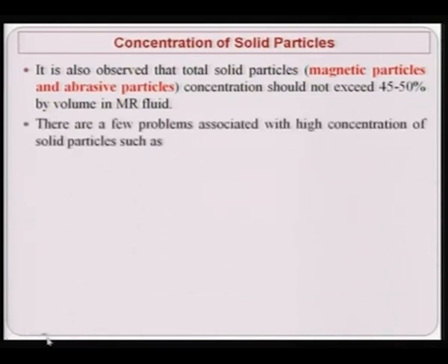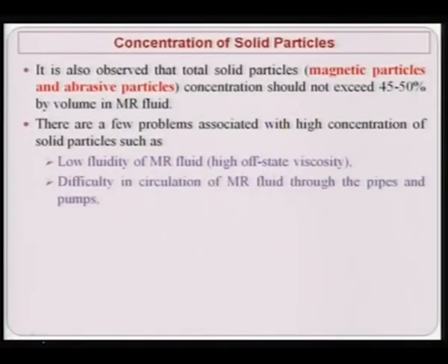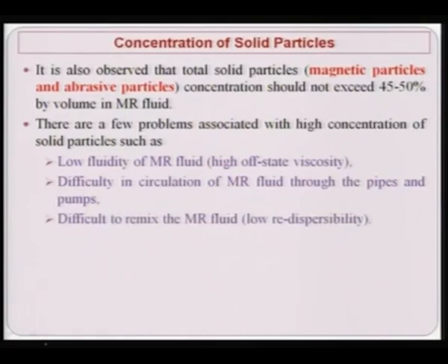There are a few problems associated with a high concentration of solid particles, such as low fluidity of MR fluid and high off state viscosity. If there is high off state viscosity, it will not be able to reach difficult to reach areas, and you may not get proper finishing, especially in the case of a complex shaped component. There is difficulty in circulation of MR fluid through the pipes and pumps. It is also difficult to remix the MR fluid because of low dispersibility.